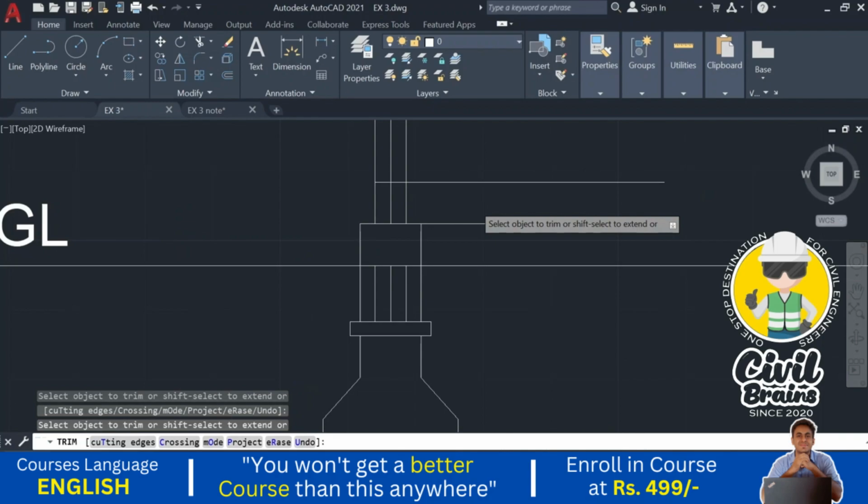So this is our ground level. So from the ground level, what is the depth of the foundation? That is 1.5 meter. I just go to the offset command, press enter, 1.5 meter, press enter. From here I take the 0.5 meter. Okay, so what is the width of the footing? We have not considered here. I just write here width of the footing.